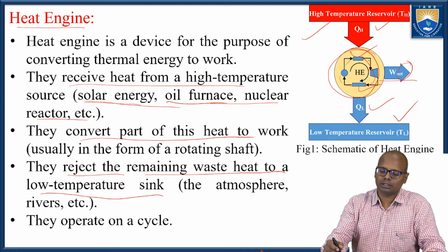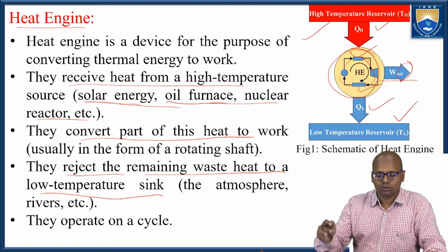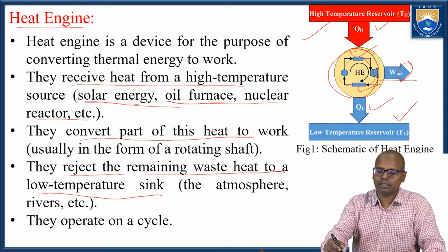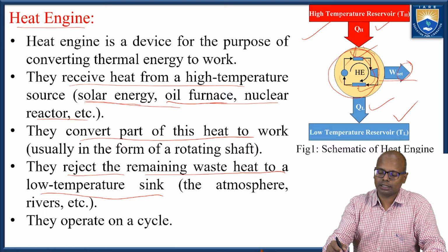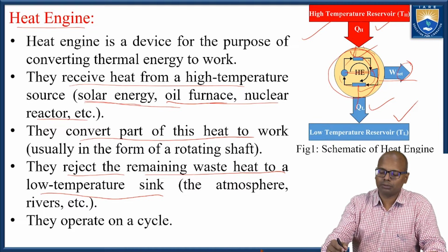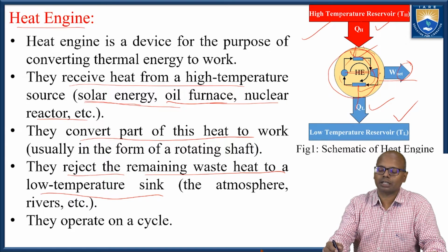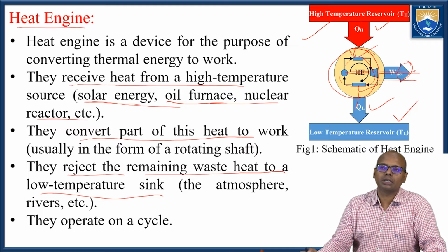So this is a turbine, heat exchanger, pump, heat exchanger. Any fluid is going in this cycle. In this heat exchanger, I am taking heat, and in this heat exchanger I am rejecting heat. The pump is connected to this turbine so that the fluid can be circulated inside this circuit, and the remaining work is transferred out to the generator.